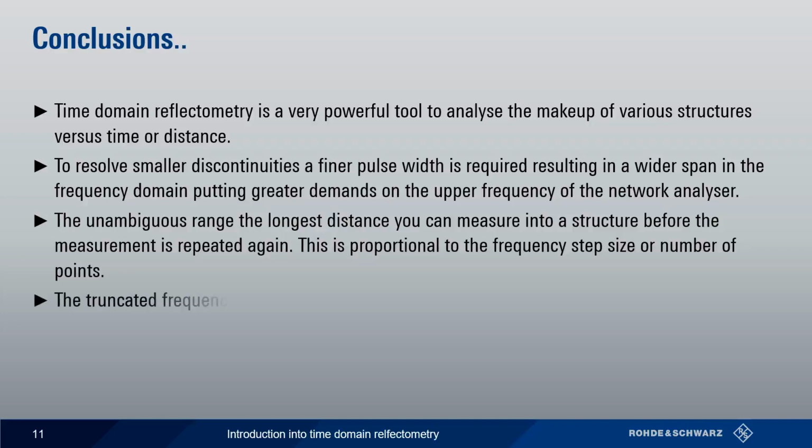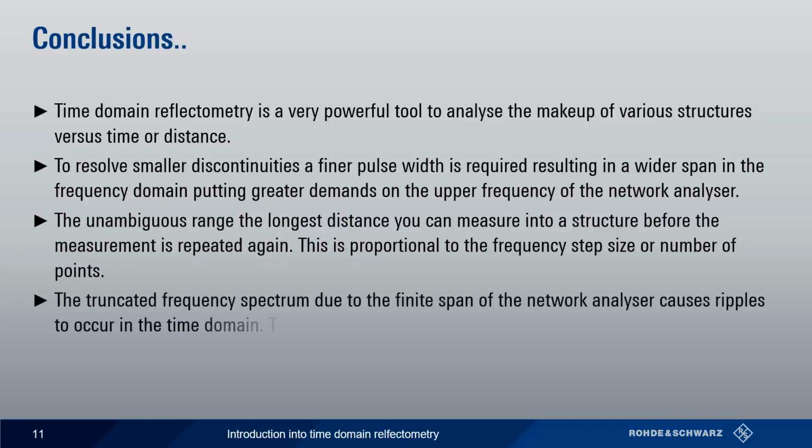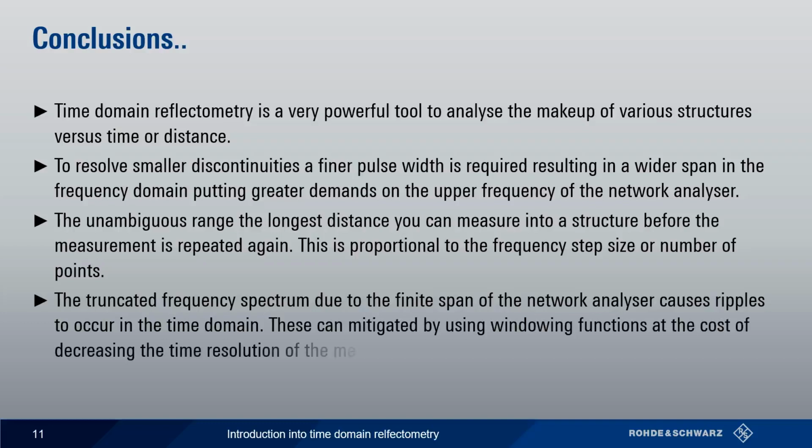The truncated frequency spectrum due to the finite span of the network analyzer causes ripples to occur in the time domain. These can be mitigated by using windowing functions at the cost of decreasing the time resolution of the overall measurement.